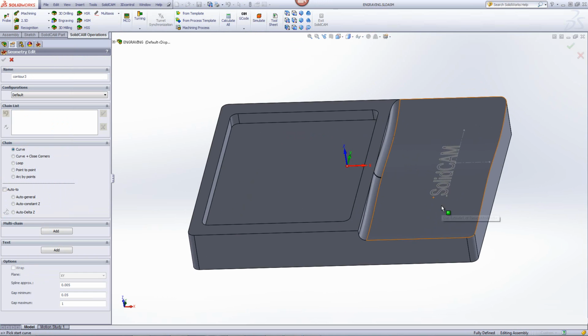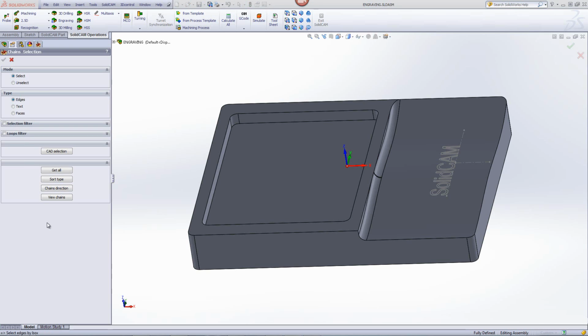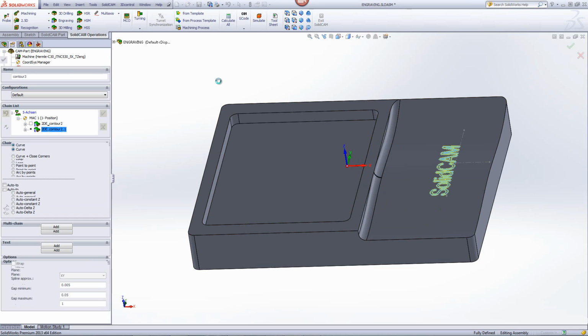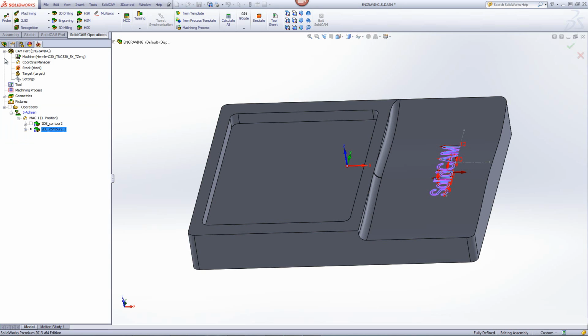By the way, I can of course use the option of text over here as well. But let me just use this text that I've done over here already. I'll choose multi-chain and choose the option of choosing my text. When I go to my text, you'll note the moment I touch the text, we have the text symbol next to my cursor. I'll click on it, accept it, and now we have a geometry for our text over there.